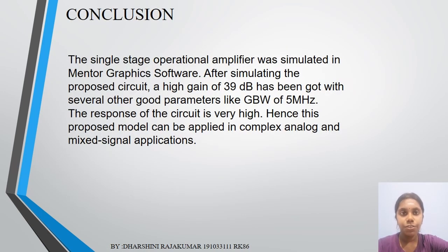In conclusion, the single-stage operational amplifier was simulated in Mentor Graphics software. After simulating the proposed circuit, a high gain of 39 dB has been obtained with several other good parameters like a gain bandwidth of 5 MHz. The response of the circuit is very high. Hence, this proposed model can be applied in complex analog and mixed signal applications.